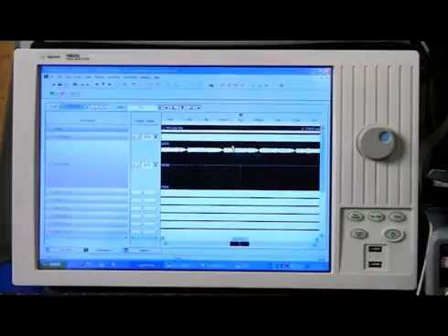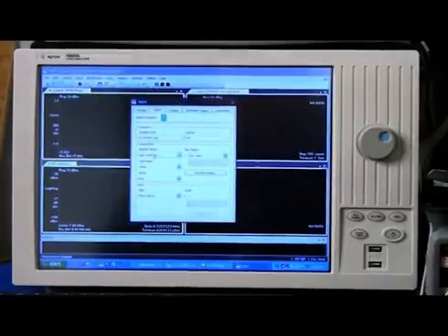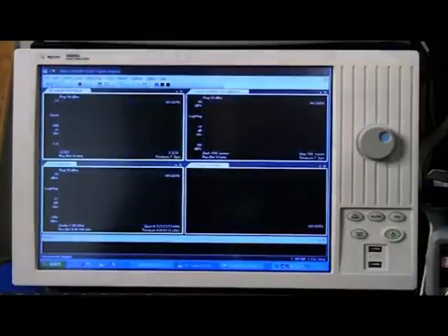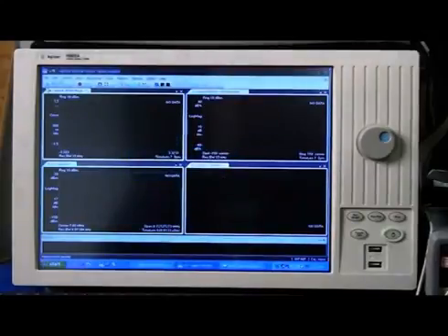We're going to look now at importing that signal to VSA. So input digital, this is where we can bring in the logic analyzer signal. There's that bus DAC input. It's a real offset binary type of format, and with that I should be able to press the run button and bring that information into VSA to view and see how we're doing.